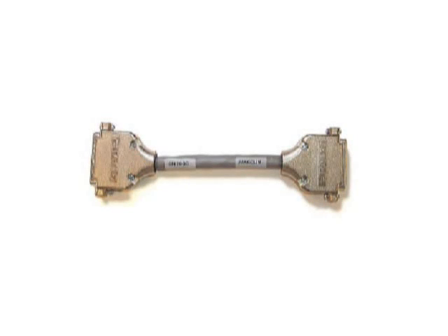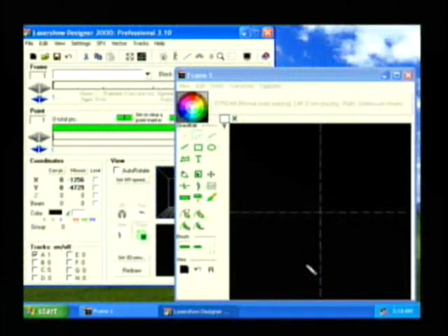If you're using a projector that's wired to the ILDA standard, then plug the male DB25 cable directly into the female DB25 connector on the Pangolin QM2000 card. If you're using a projector that's wired for the older Pangolin QM32 standard, plug your male DB25 cable into the QM2000 to QM32 adapter cable provided, and then plug that into the QM2000. Once we've connected our projector and powered up the necessary components, we're ready to display images.